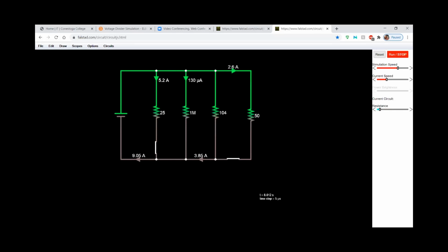Okay, perfect. So just to finish this, when we have our 52 ohms, yes, indeed, we are going to have our 2.5 amps. But if I simulate that we have an open resistor, then we are not going to have any flow. So we are going to lose our current flow through that ammeter, and it's just going to be reading 0. And because we opened one of the branches, now only 3 branches are accounting for the total current flow that we have through A1. Any questions about that?